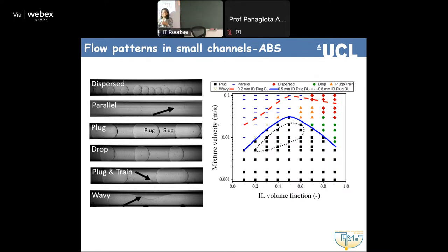This might be very nice because if people start thinking about mass transfer resistances, you have the least mass transfer resistance when you are all in one phase. So you can think creatively: if I do it like that, my mass transfer will happen and I put in my metal or whatever very quickly, and then make the two phases separate. It will be more tricky to handle and control as a system, but there is a possibility there.